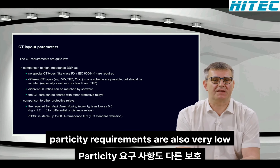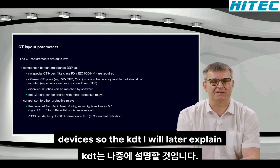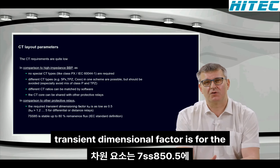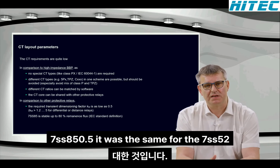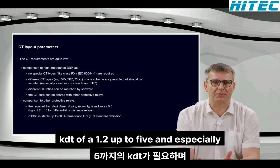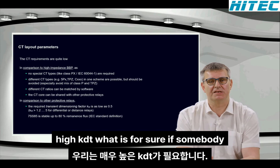But the CT requirements are also very low in comparison to the other protection devices. So the KDD, I will later explain how we come to the KDD. The KDD, the transient dimensioning factor, is 0.5 for the 7SS85. It was the same for the 7SS52. For transformer differential protection and line differential protection, we need a KDD of 1.2 up to 5. And especially for distance protection, we need a very high KDD.